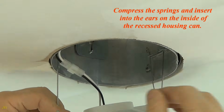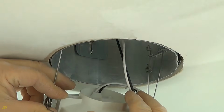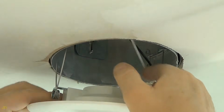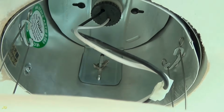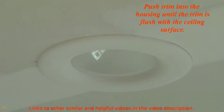Compress the springs and insert them into the ears on the inside of the recessed housing can. Push the trim into the housing until the trim is flush with the ceiling surface.